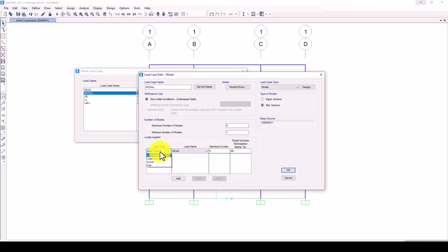We can actually consider the acceleration, actually not the load. We want to apply the load, which is deformation, and to give us the displacement, it should reach at least 95% of the mass participation. So it's X, and we also can ask for the Z, so vertical, because we have 2D. We just ask X and we ask Y or Z. So this is 2. It means mode shape in the X direction, which is getting the natural period and frequency. This Z direction in vertical.